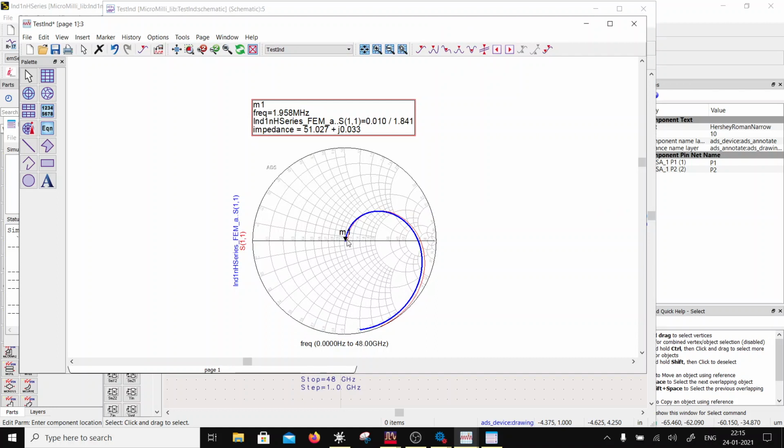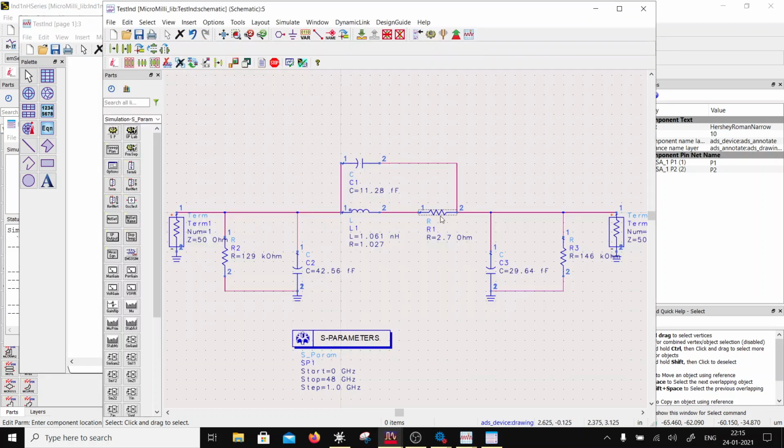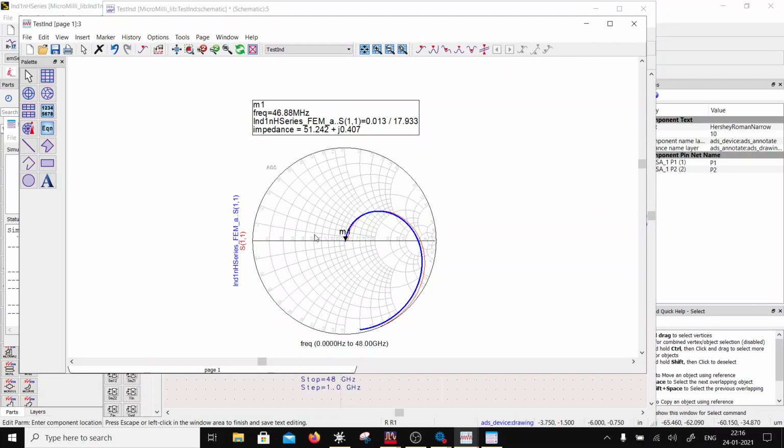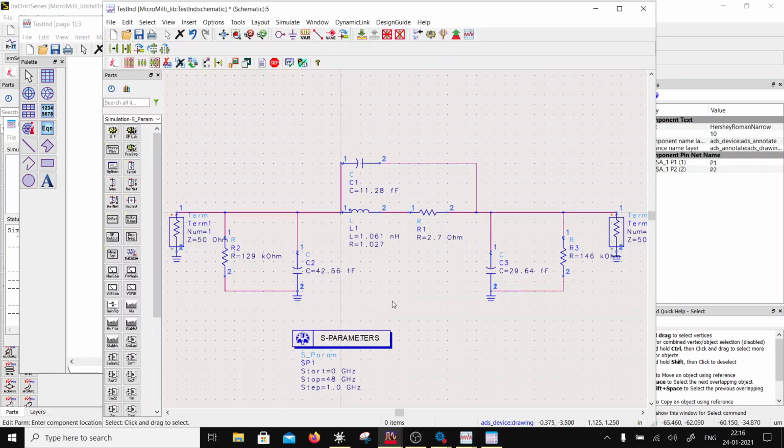Oh, that frequency dependence term of RAC. This RAC is coming as 2.7 because it is put as fixed, and that's not what we are supposed to do. So we have to put in here a formula for this, a linear approximation. We have to go with the square root of frequency. Is there a square root of frequency term that will bend over?